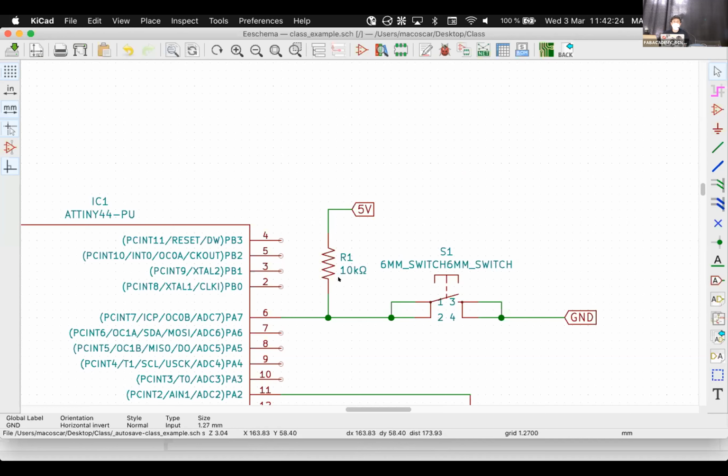Exactly, yes, we consume some current when the switch is off. Either way, some current is going to have to go into that pin. And then internally, since you have this high impedance state, it means that inside the microcontroller, you have a very, very large resistor in that pin. And that makes it very sensitive.